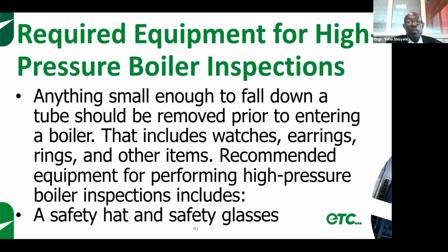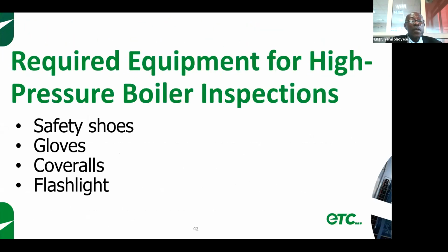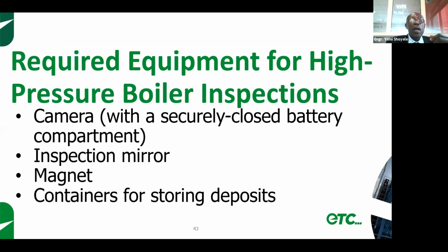Okay. Now, the recommended equipment for performing high pressure boiler inspections include: 1, the safety hat, the safety glass. You must have that. Safety shoes, your gloves, coveralls, and your flashlight. These are things that you must have with you, or you must have on you before you go into the boiler. Camera,